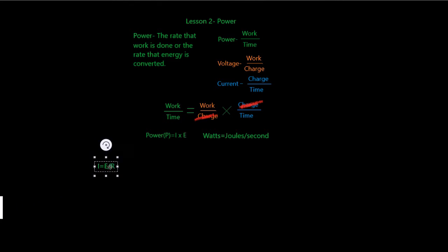Now, if you look, we have current and voltage equals power. But we've already established in our previous lesson that current and voltage have an established relationship within a system. They relate through R. Current is equal to voltage divided by resistance. That means that from this equation, we can actually make two more. This will come in handy whenever we have to calculate the power in a system where maybe we don't know the voltage and the current. We have two other equations where we utilize R.